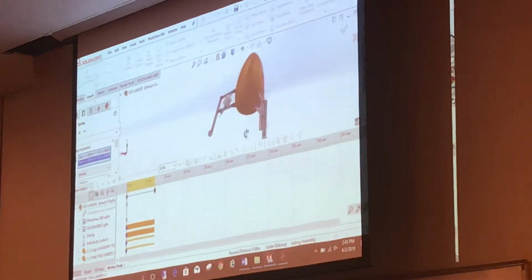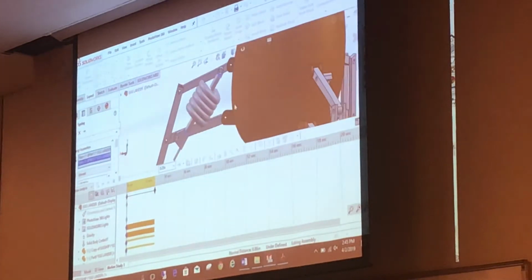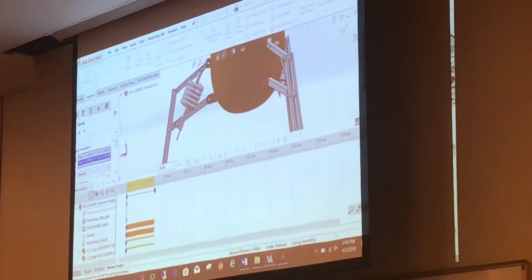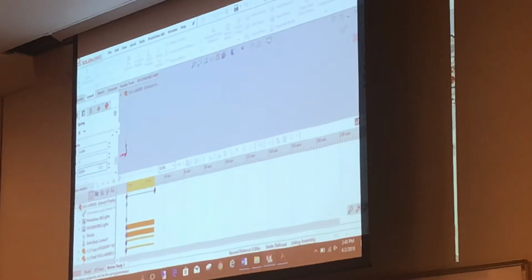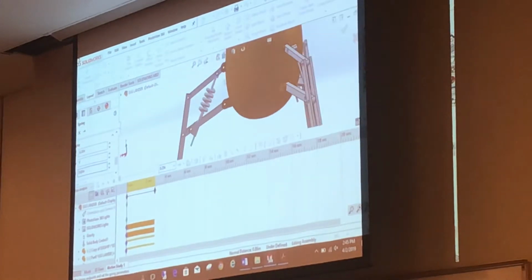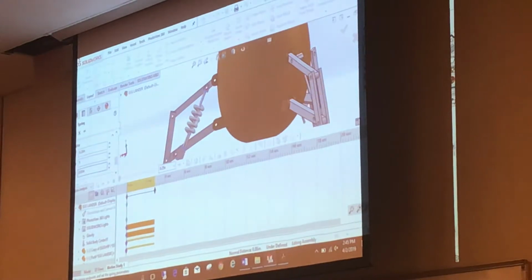Okay, and we get this big old beefy spring. That's like the Arnold Schwarzenegger version of a spring. But we can tame that display down if we scroll down here to its display parameters right here. And let's just make the coil diameter about half as large. We'll make it 0.2. We'll make the wire diameter about half as large. Okay, so that's a more reasonable spring. But changing the display of the spring has no effect on its properties.